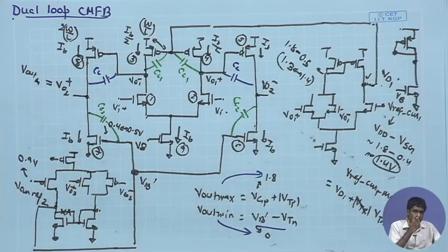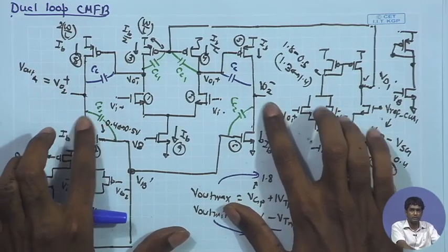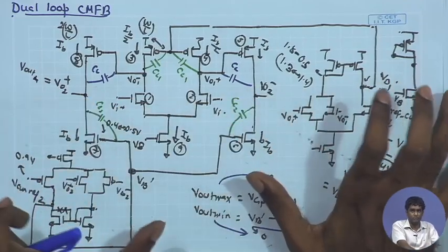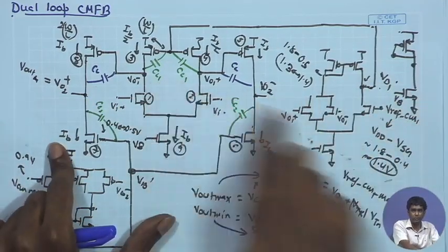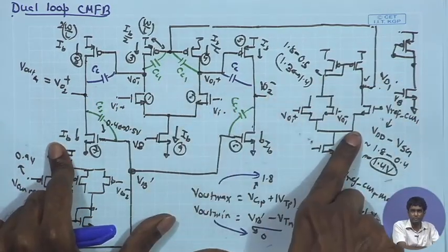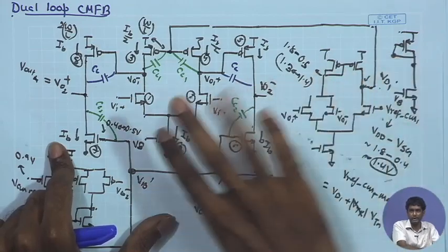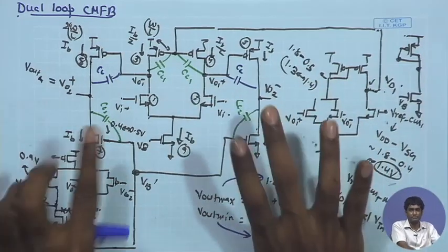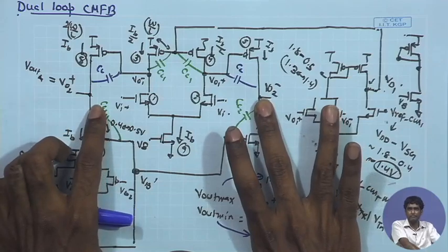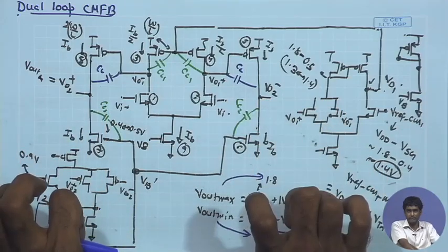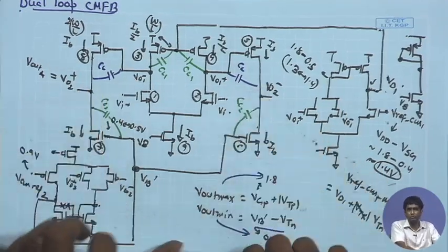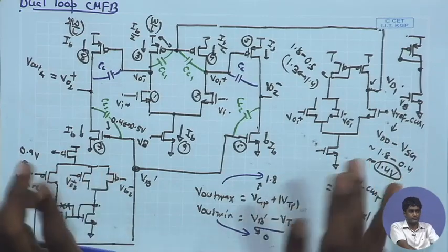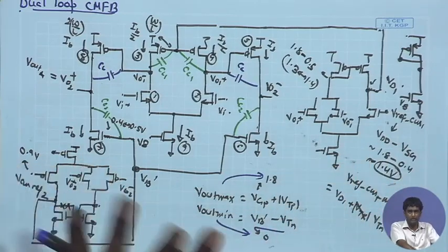So, that already gives you better stability for the differential loop as compared to the common mode loop, where you have the overall loop gain given by GMRO times GMRO, that is maybe 30-40 times larger than the differential loop. So, compensation for the differential loop can be easier if I consider that beta factor, and then the required CC value may also be smaller. So, that can make a greater difference.